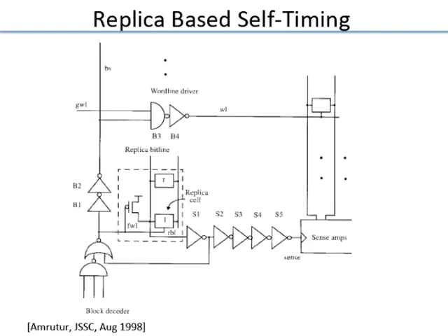So how do we now generate the SRAM timing? Basically, I just want to introduce this concept of self timing. It's a very interesting concept where you generate internal timing. There could be other applications where you have to generate multiple timing signals, and then internally you generate these signals locally. You don't rely on a clock, but internally you are somehow generating these various edges. So this is one particular application.